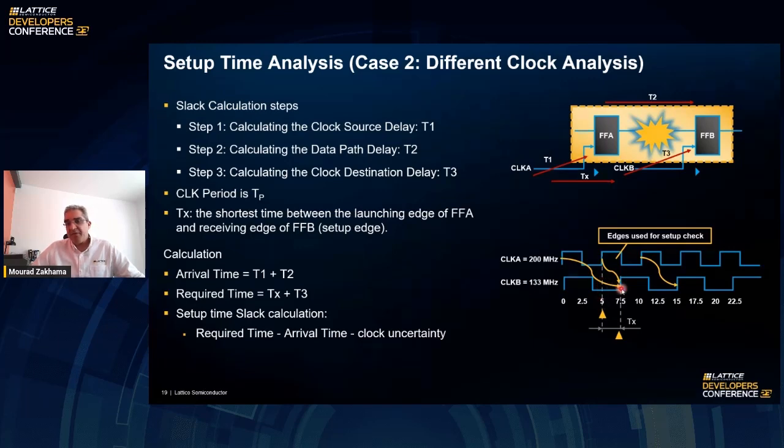This is what we call the clock domain crossing situation. Ideally, I would say we need to cover that by some CDC circuitry, either a FIFO in between or some cascaded registers to avoid the metastability situation.